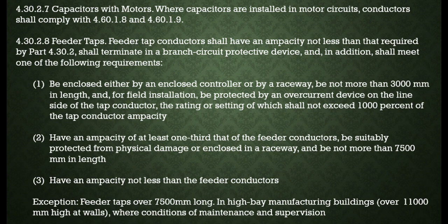Feeder tap conductors need an ampacity as per part 4.30.2 and must terminate in a branch circuit protective device, also meeting one of these: enclosure within 3000 mm with overcurrent protection rating not exceeding 1000% of tap ampacity, and ampacity of at least 1/3 of feeder conductors protected from damage within 7,500 mm, or ampacity not less than the feeder conductors.